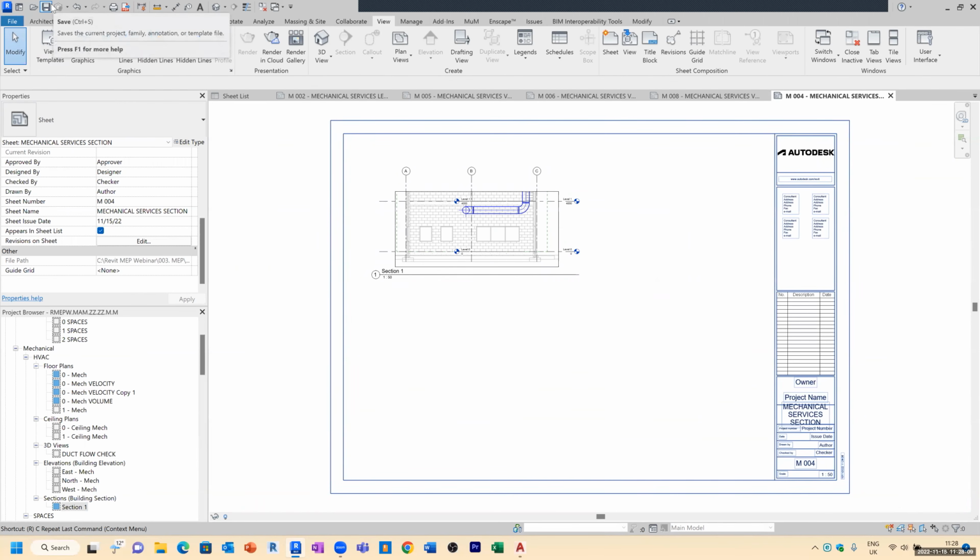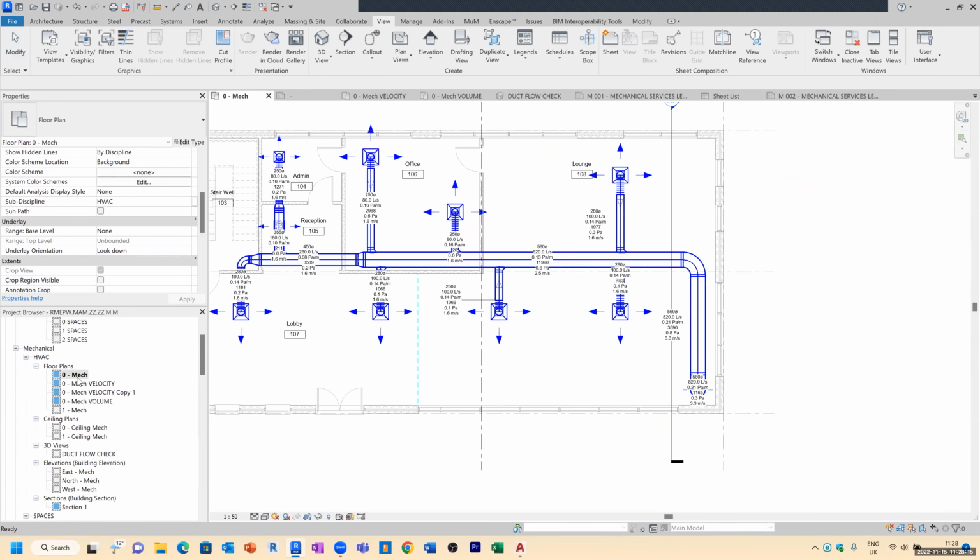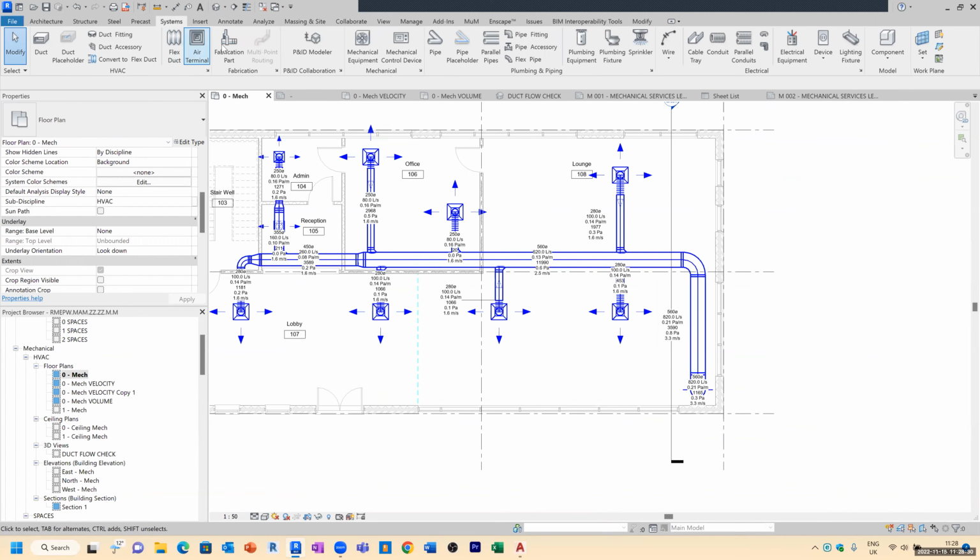And so finally, I know time's getting on a bit now. Let's save this project. Finally, you'd want to push your design into some sort of fabrication package ready to go to your duct fitters, etc. My advice here would be to, before going into your fabrication function here, save your model into another version to use as your fabrication model.